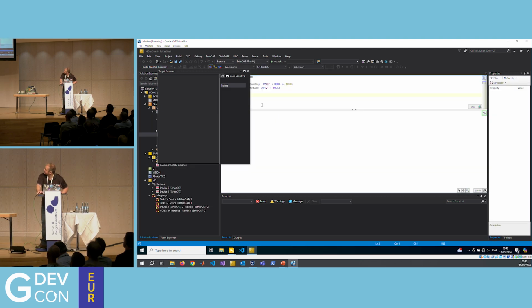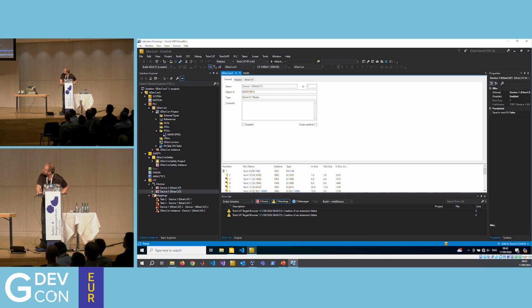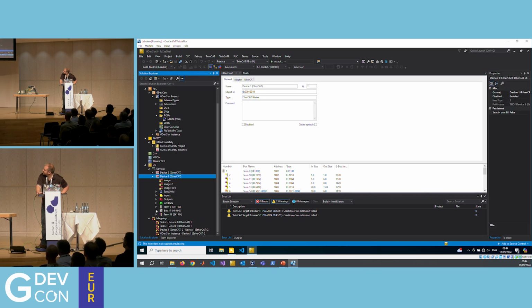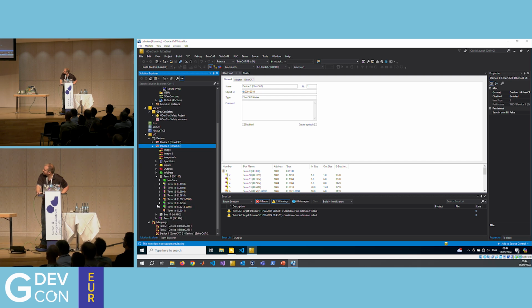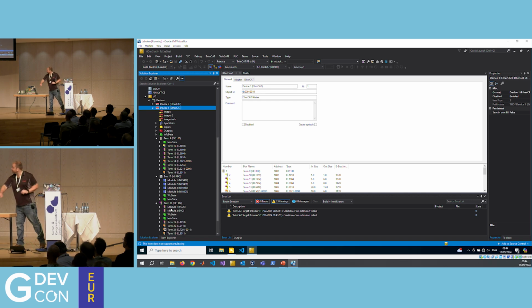So in TwinCAT, all I actually have, come down here, is my EtherCAT network. In here, you'll see the first bank of I/O with our devices in there, the NI chassis, and then the second bank of I/O, which is just the two couplers on this system. So we have a servo drive in there, which if the demonstration was working would spin, I promise.